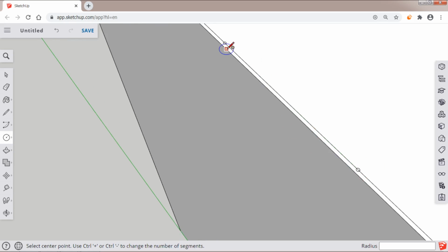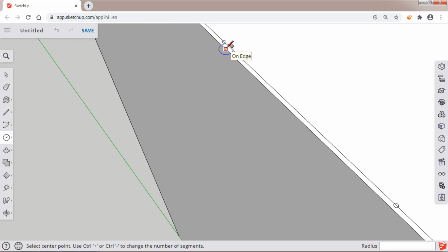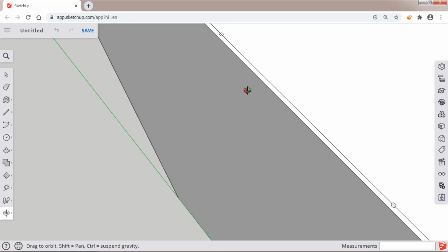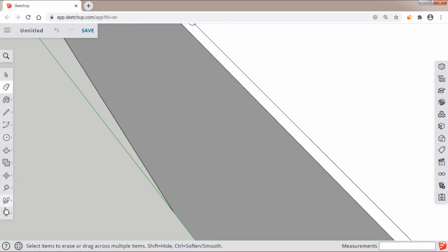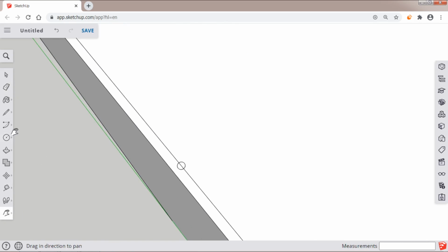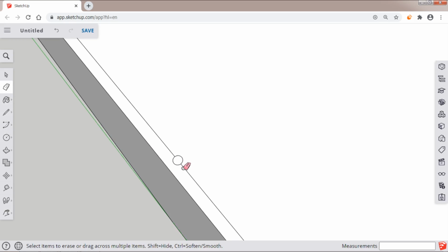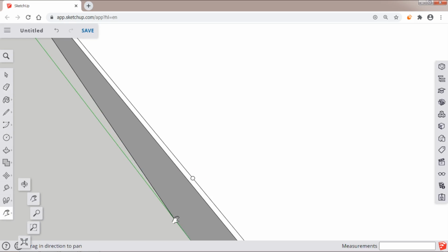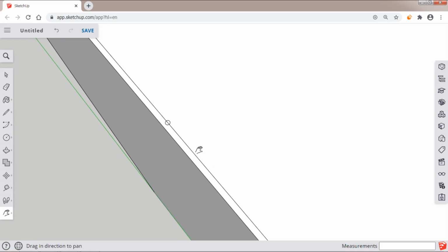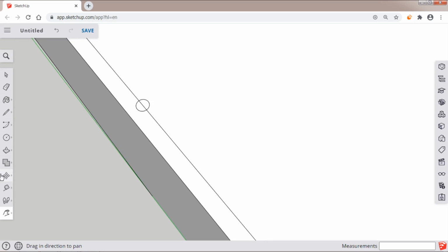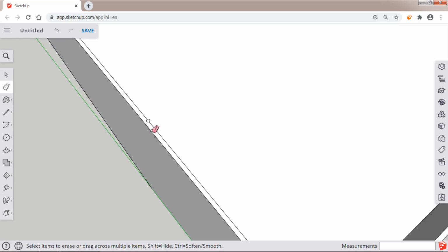Once we have finished drawing the circles, the middle line is shown, and we need to erase the middle line inside the circles. So with the help of the pan command, we pull this diagram over here. With the help of the eraser, by zooming in, we erase the middle line. Once again with the pan command, we erase the line between the circles like this.